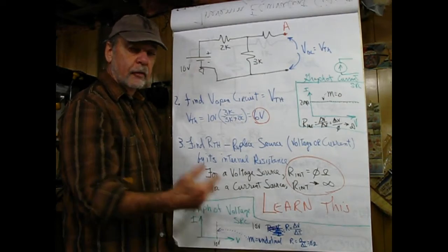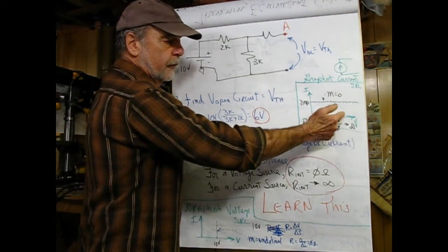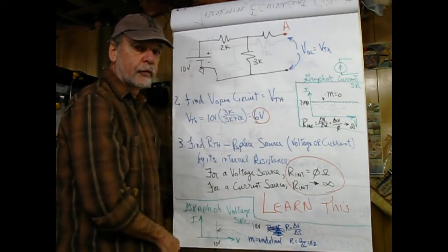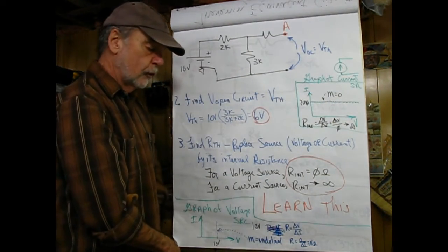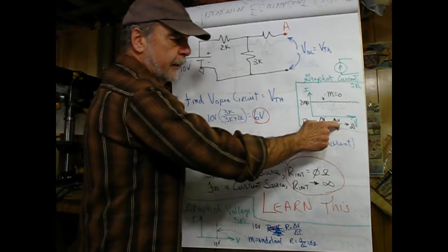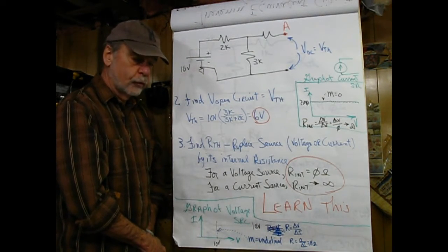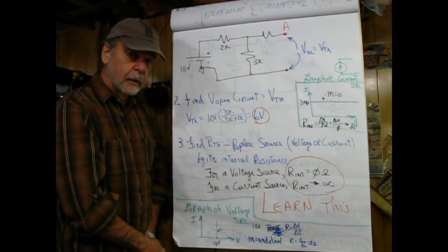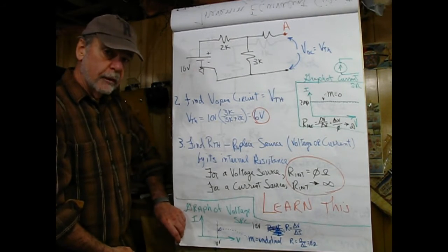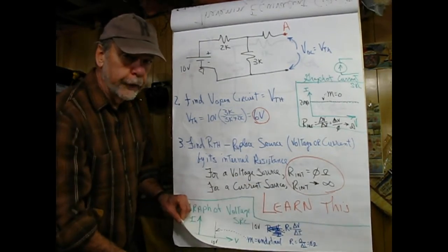And what we can see here is we certainly can have a delta V. Any two points on this line would give a delta V, but the delta I remains constant. So you'd have some value, and from that would be subtracted the same value, which gives 0. And that would be, if we took the limit of this, undefined, and in our case, we're going to look at that as an open circuit. We can consider it to be an infinite amount of ohms, infinite resistance. Learn this.